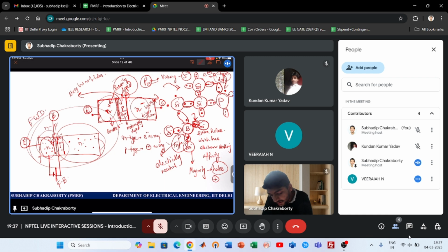Once we forward bias, because we have doped it heavily, the majority charge carriers, which here are the electrons in the N, will jump and cross the barrier, because the external electric field of the battery, what you call the forcing field, is more than the depletion field, and slightly it will reduce it, and the charge carriers will be crossing into the region.